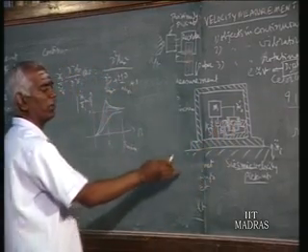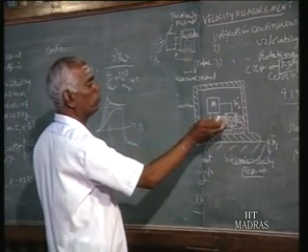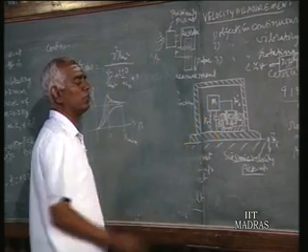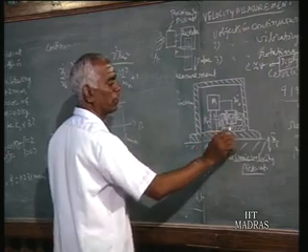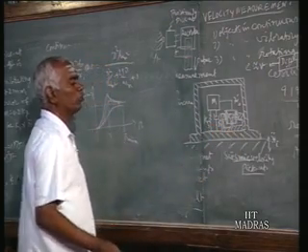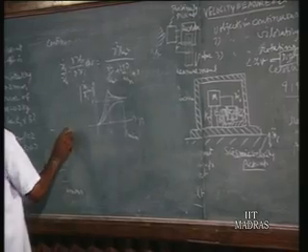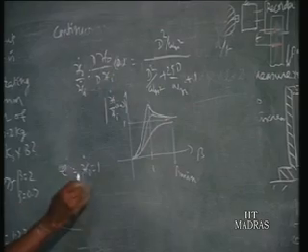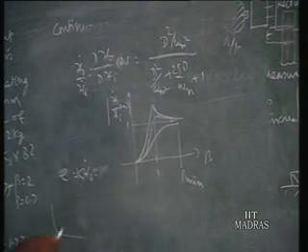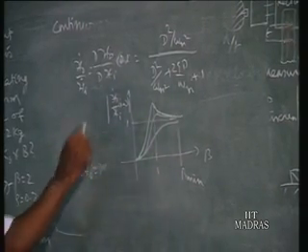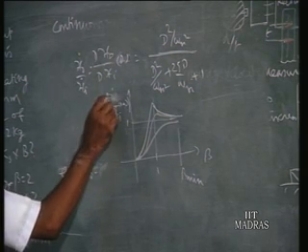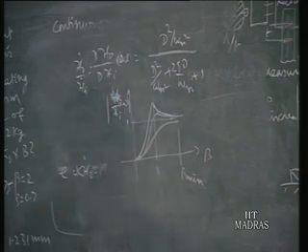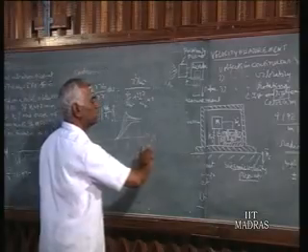So for measuring xo dot, I have used here the moving coil, moving magnet pickup. Here the coil is connected to the mass, so the relative motion of this mass with reference to the frame is measured, and the magnet is fixed to the frame. So the voltage output E is equal to k times xo dot. So you can write xo dot as E over k, that is again 1. That is, we are measuring the output voltage as velocity.